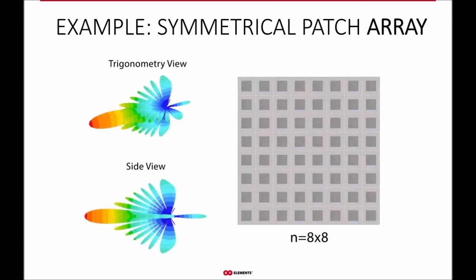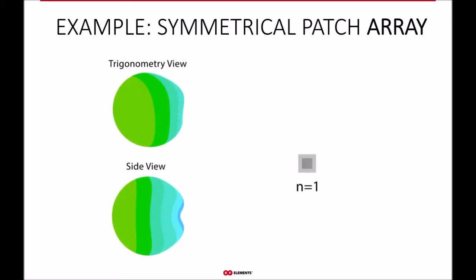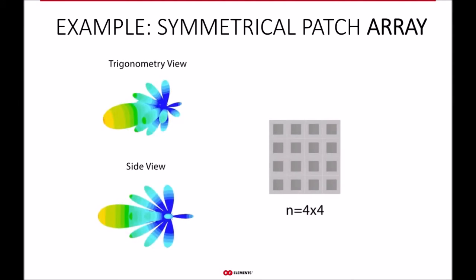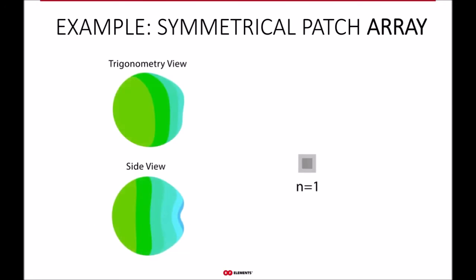And by now, I'm sure you're getting the intuitive understanding of how the antenna arrays work. So if we, for example, stacked patches only along the horizontal direction, the radiation pattern would be getting narrow in the azimuth plane, and elevation would, vice versa, again, remain the same.